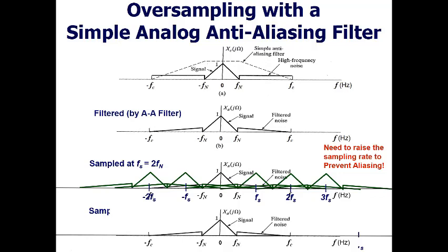If we could raise the sampling rate, however, so that the Nyquist rate is no longer the edge of the original frequency content, but this point where the aliased signal is pretty much gone, then when we make the spectral copies, they're all going to end up way out here at integer multiples of Fc, and nothing's going to alias anymore. Some of those are obscured, but in this case, by choosing a much higher sampling rate, we can prevent aliasing from happening.